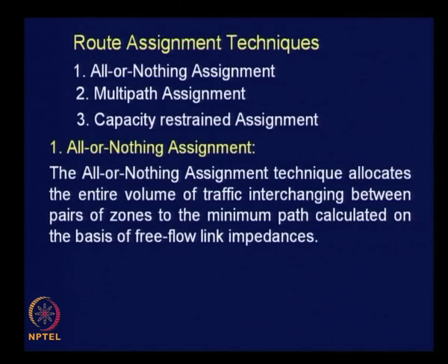This technique allocates the entire volume of traffic interchanging between pairs of zones to the minimum path calculated on the basis of free flow link impedances, right. That is why this is called all or nothing assignment technique. You assign the whole of the traffic to a set of links or nothing to a given path. Okay.